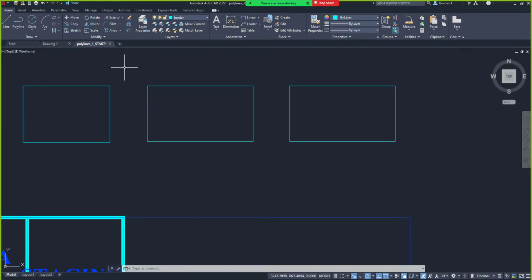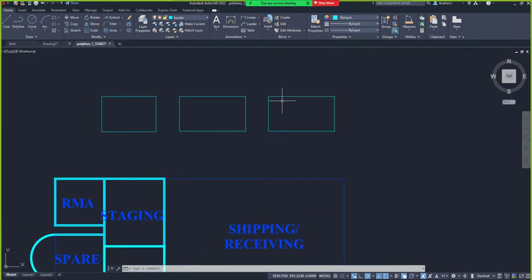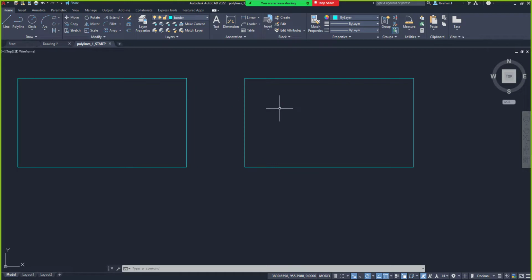Are you with me? If you know you want to add your width, just use your normal offset, and then you can work around your offset, or you use your width directly and leave the object as a polyline. But like I said, every design choice that you make is according to whatever you are trying to achieve in your mind. Do you understand? Or whatever project task you have in front of you, it will usher you into the kind of tool you are going to use.